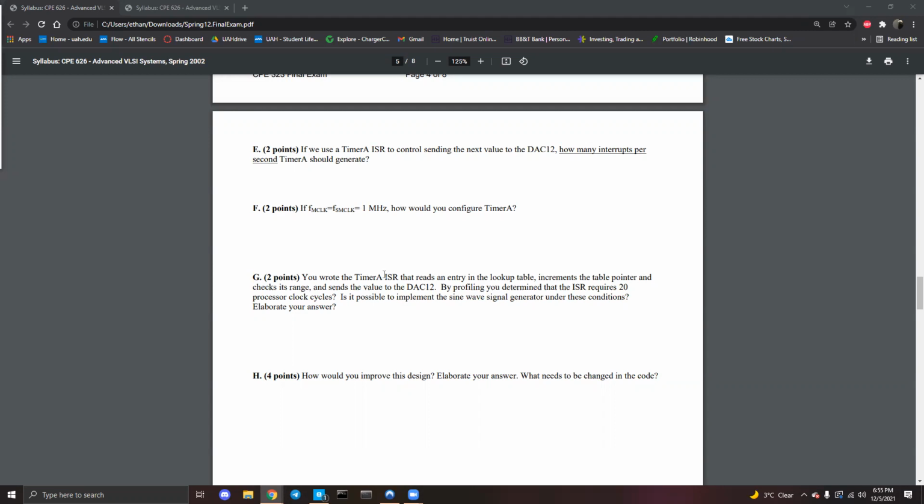By now I have a disgusting amount of experience with timers because I'm a sad little boy, right? So all you do here to get your R0 value, that is your peak count, which also counts as, if you have nothing else and just that value, every time it reaches that count, it'll spit out an interrupt, right? So you need the decimal number to put into the register with your source clock, so you can count to your 20,000 hertz. To produce that, you do 1 megahertz divided by 20,000 hertz, and that will spit out a decimal number for you.